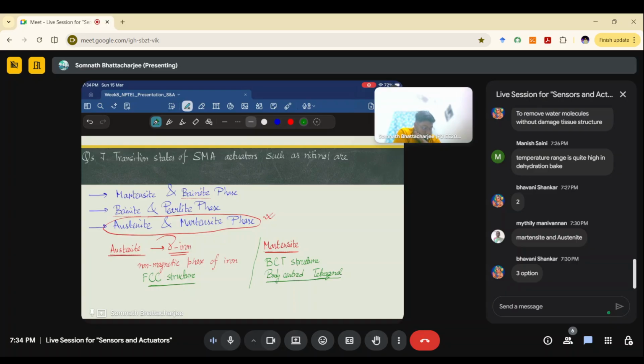So this is kind of a metastable state, right? It is not a completely stable state. Because of that, it can come back to the previous state if we give it very high heat or something like that. And it is also a brittle state as well, right? A very brittle and metastable state, and it can come back to this austenite stage, right?